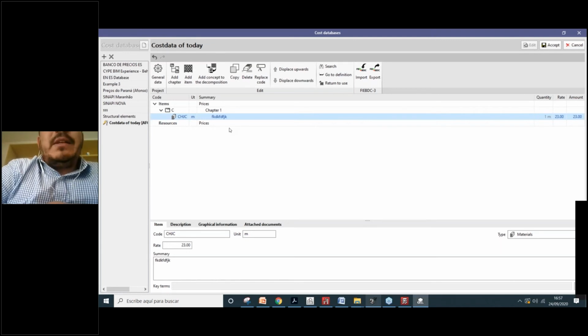You can create your own cost database here. You can also import using the BC3 format. BC3, like the IFC format, is the standard Open BIM format for view of quantities. So you can send and receive information related to the price of these items using this format. For example, CYPE Archimedes is another software in our suite for project management, to import and export BC3.